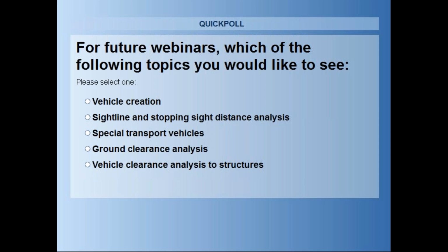What kind of turns is it calculating for the IntelliPath compared with placing the vehicle and simulating the turning path myself? Well, the movements that IntelliPath calculates are based on the steering of the vehicle. So the vehicle will try to steer and will be constantly adjusting the steering so that it can accomplish the maneuver. So yeah, that's the difference. It works more like autonomous vehicles, where they are scanning boundaries and trying to keep the vehicle centered or within certain parameters.